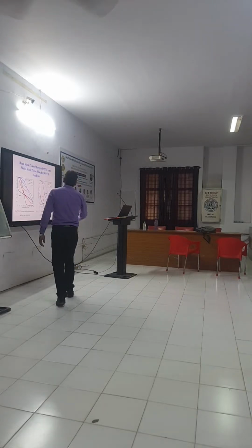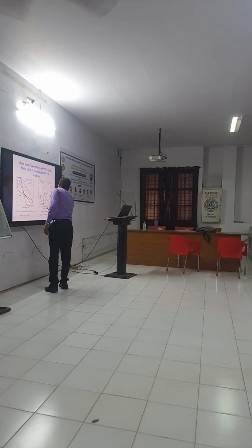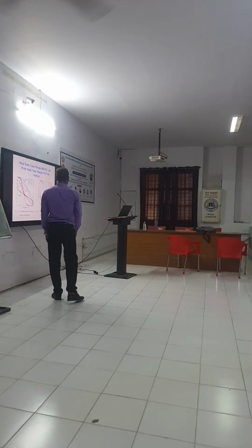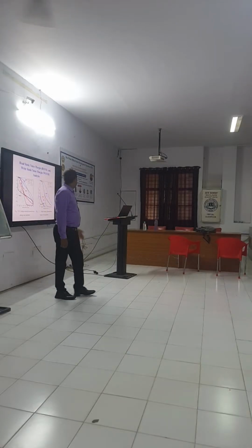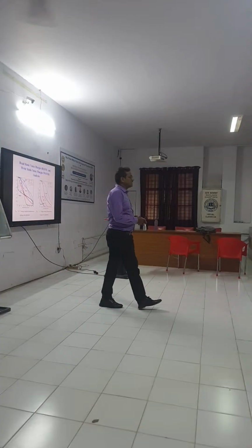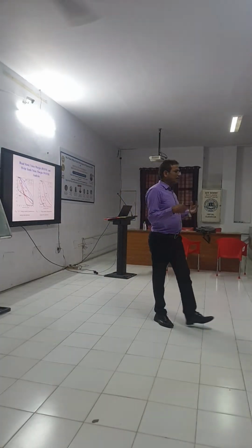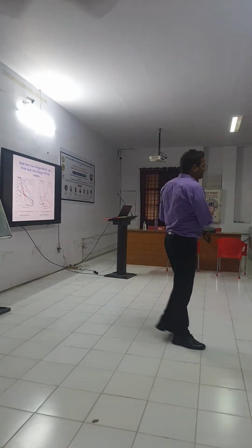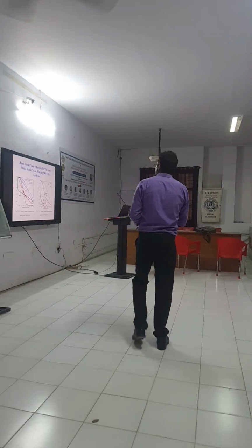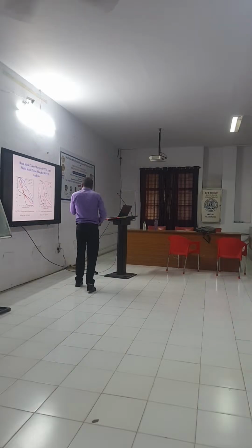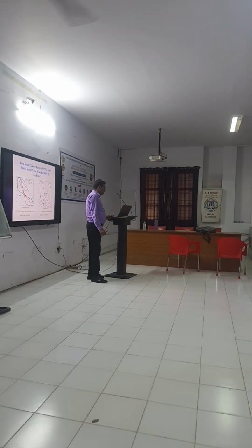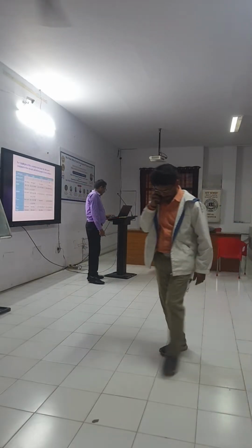So this larger square, it is very high. This one is 150 millivolt. Conventional 8T is 50 millivolt. So our WSNM is very high. So during write time, more noise can come and be tolerated. So this is the write noise margin. That is a yes.